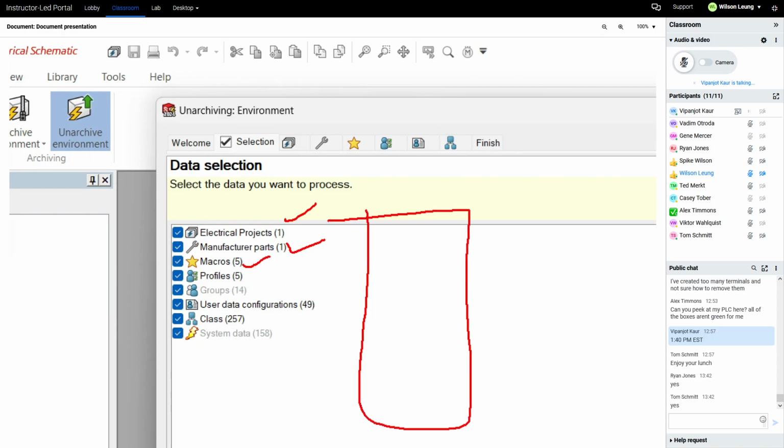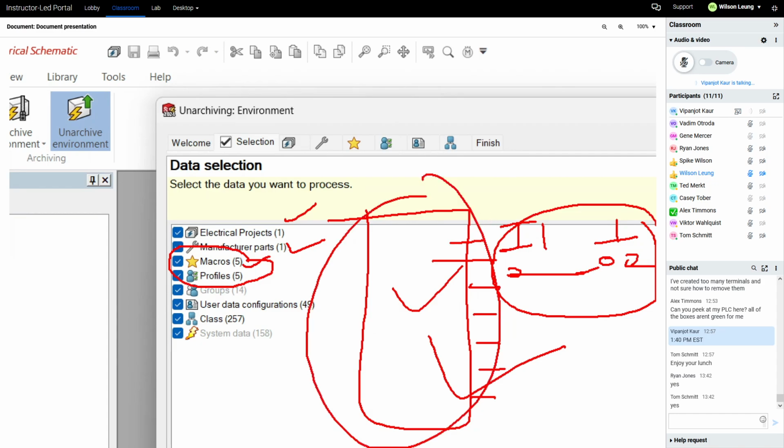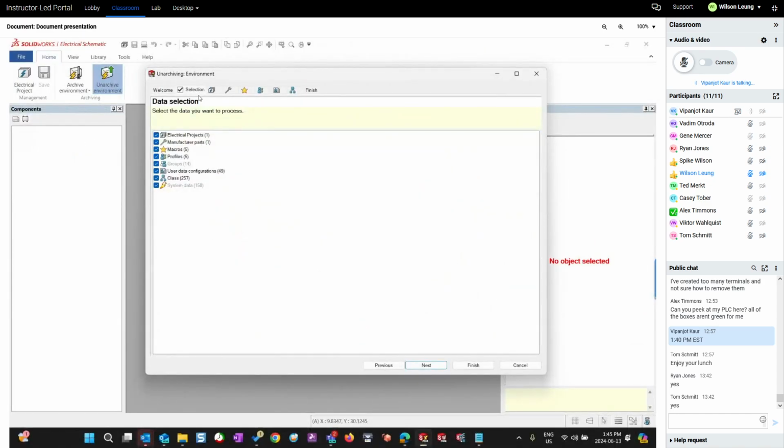So if I have a PLC symbol, and let's say Alex tells me, for your first input, I want you to show a wire so and so, show a push button, and then show a wire continuing after the push button. So I have different macros that they're giving us in this lesson that we can use, and we can link macros for each and every input and each and every output. So not only our symbol, but also our detailed connections, the wire connections will be completed using this process of inserting PLC symbols.